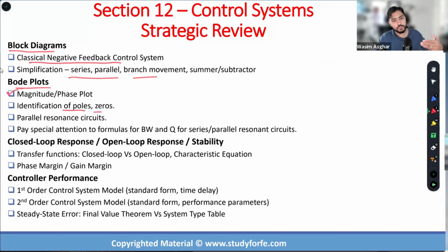And the next step from there is to come up with a generic equation of the transfer function. And then the final step is to figure out the value of K, which is a steady state gain. And as I mentioned earlier, you can even be given a transfer function and you might have to reverse engineer the transfer function into a Bode plot. Okay, so everything is possible.